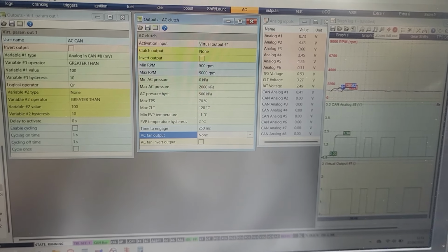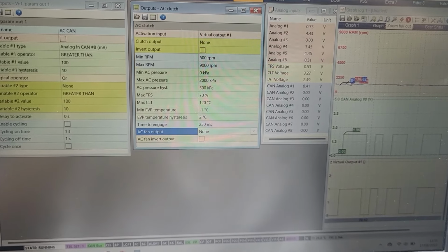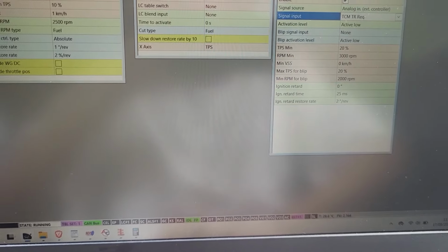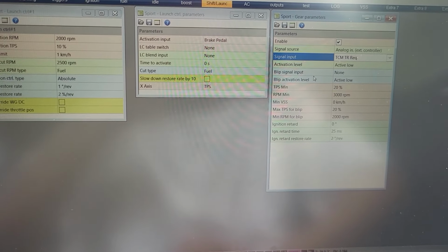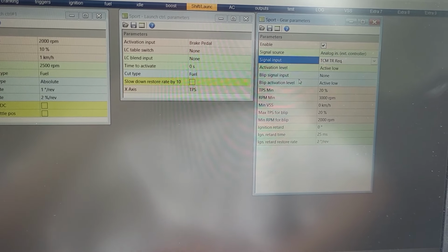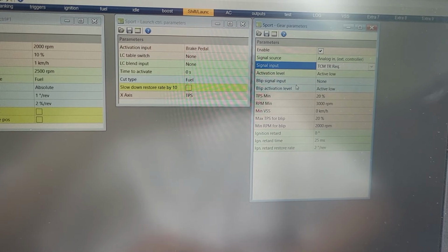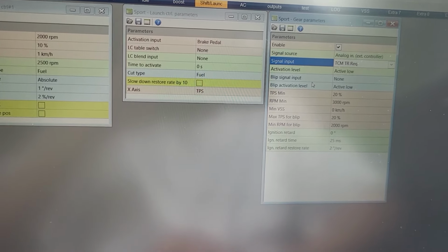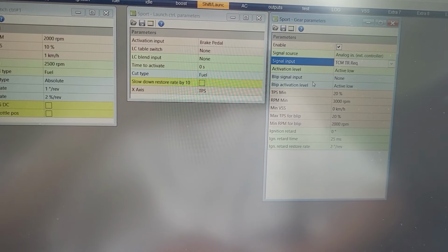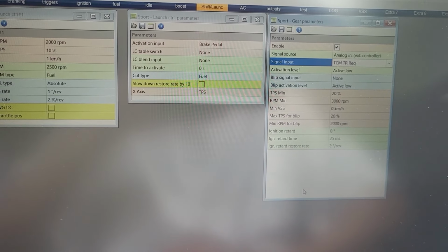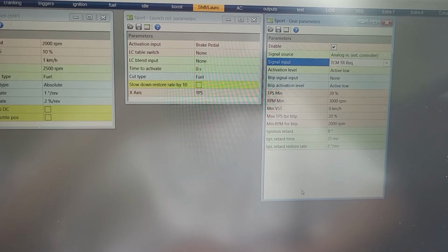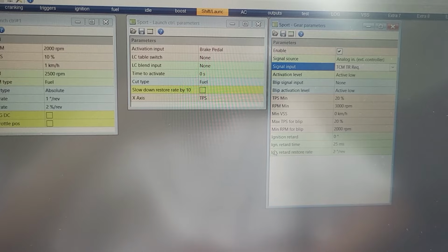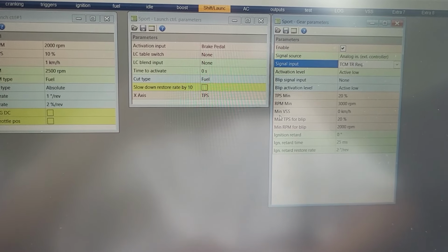So what am I going to do next? I've already got this torque reduction request set up. I originally, and I've shown it in previous videos, had a custom table whereby when that message came through, it retarded the ignition by a little bit. There's actually better strategies built into the EMU Black. I was trying flat shifting, but after a lot of reading last night, I think gear cut is going to be a better one for me.